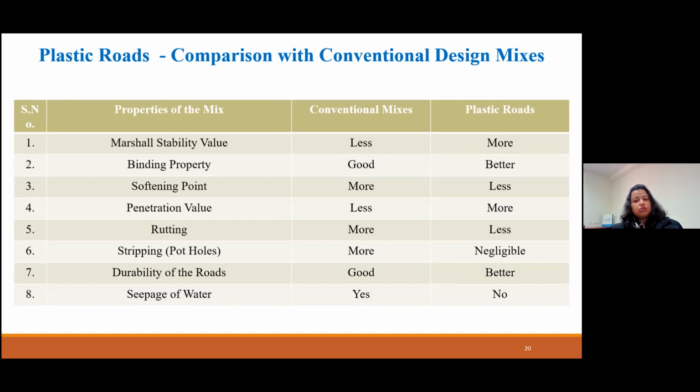So on rural highways also, it is very beneficial to use plastic roads, because other types of design mix have a constraint with heavy traffic movement and how they take the axle loads. Plastic roads perform exceptionally well in terms of rutting, and the adhesion between bitumen, the waste and the aggregate is such that stripping is also negligible. In the stretches where they have been laid, performance assessment was done by CRRI and CPCB, and I'll discuss all those in the coming slides.